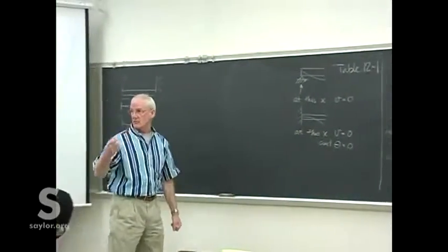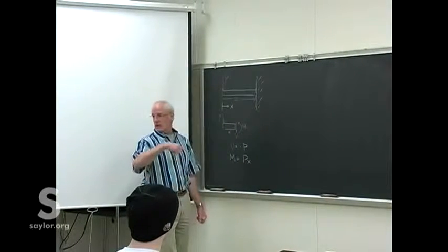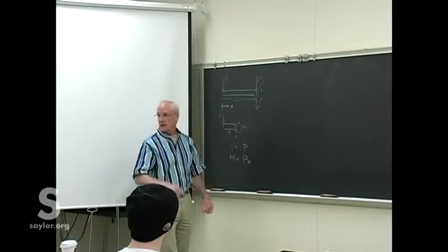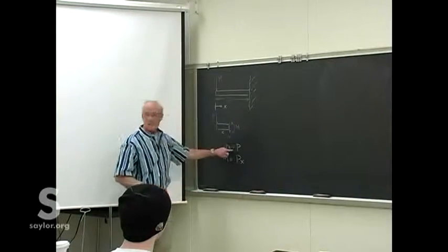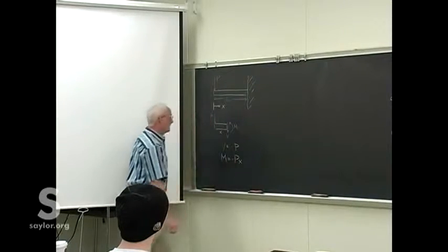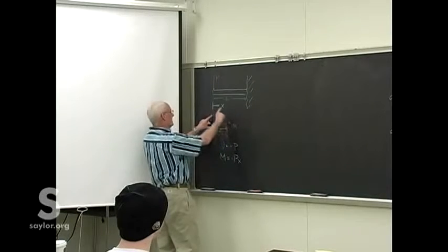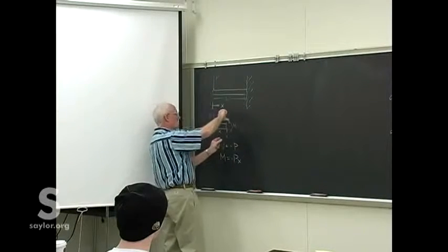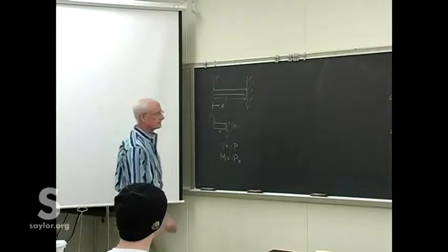We're going to have some loadings where the deflection will be down and some loadings where the deflection will be up, depending on how the beam is bending at certain places. And we're going to need that minus sign to carry all the way through. So there's a minus sign on there too, because the shear is actually up, turning the beam that way. We need a moment that way, so we'll have a minus sign there.